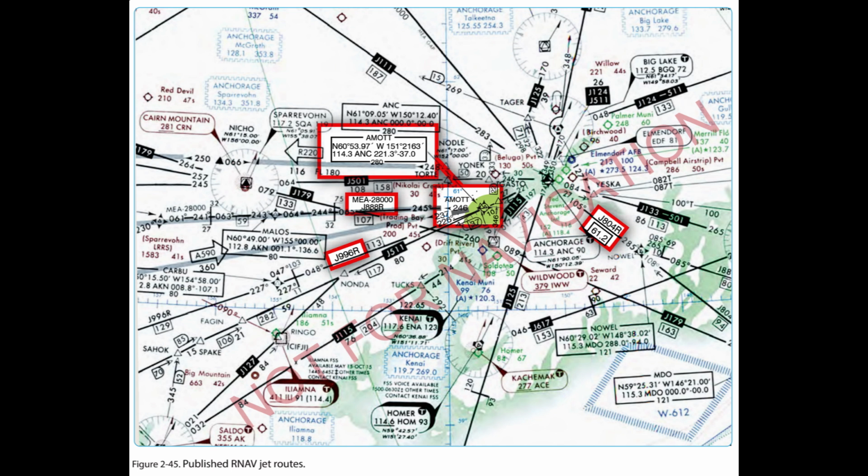Use of designators in communications. In voice communications, the basic letter of a designator should be spoken in accordance with the International Civil Aviation Organization (ICAO) spelling alphabet. Where the prefixes K, U, or S, previously mentioned, are used in voice communications, they should be pronounced as K, Copter; U, Upper, as in the English language; S, Supersonic. Where suffixes F, G, Y, or Z specified above are used, the flight crew should not be required to use them in voice communications.